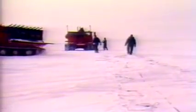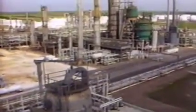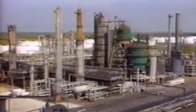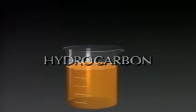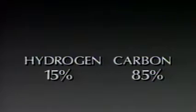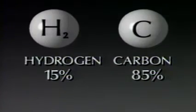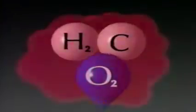Oil deposits beneath the ground and the oceans of the world are the source for crude oil, which is then transported to refineries. There, the many oil products are drawn out of the crude through distillation and other processes. Then the oil is shipped to oil dealers for sale to the consumers. Fuel oil is a valuable heating source because it is a hydrocarbon. Taking that name apart, you see that the fuel oil hydrocarbon is 15% hydrogen and 85% carbon. Both hydrogen and carbon are flammable when combined with oxygen in a chemical reaction called oxidation, or burning.